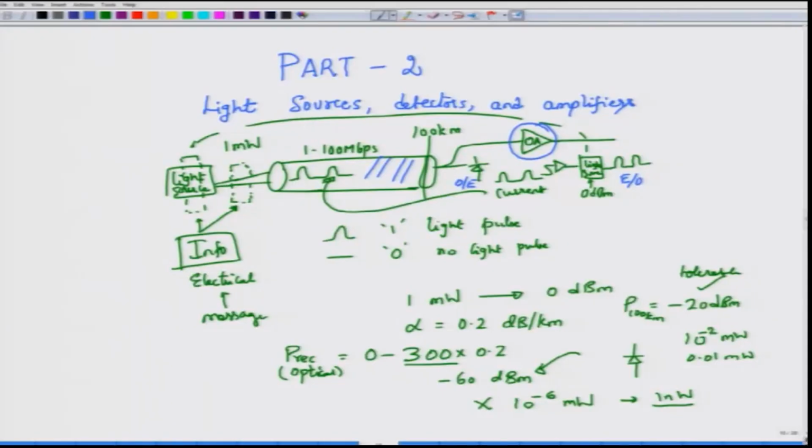And of course, we do not really have to do that, because luckily around the mid 1980s people discovered or invented the optical amplifier, so that you would never have to convert the optical signals back into the electrical domain and again convert from the electrical domain to optical signals. And the prominent optical amplifier which was studied first and then brought into the market is called the erbium doped fiber amplifier. Okay.